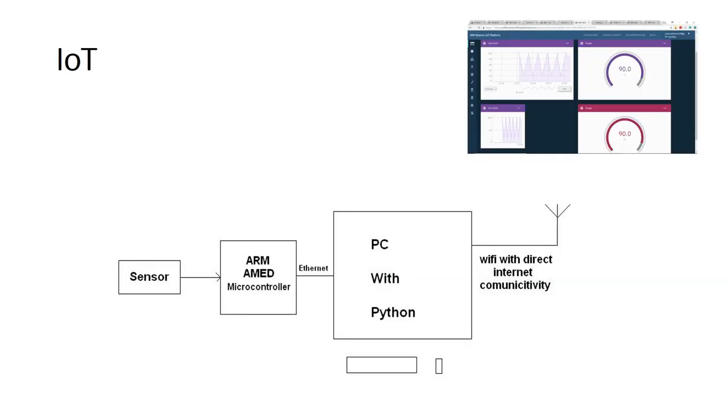Now the same thing, if you want to create a client in an IoT, the same device you can use, and you can have a small little Python code which will read the temperature from 192.168.1.133 and convert it to a JSON format to be sent to Bluemix or something, and you can see a Bluemix screen where the data can be displayed.